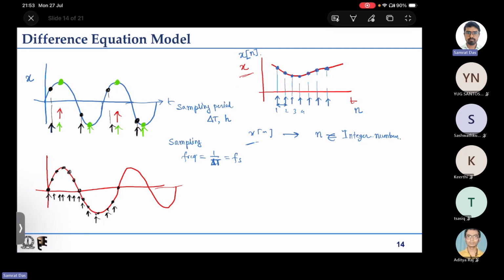So here you can see that the dotted points, if this is the discrete representation of the signal, reasonably represent the nature of the signal. Yes, it could be better if we go for higher and higher sampling frequencies, but it is reasonably good if it is at least 10 times or higher than that. So this is what we discussed briefly last week also.